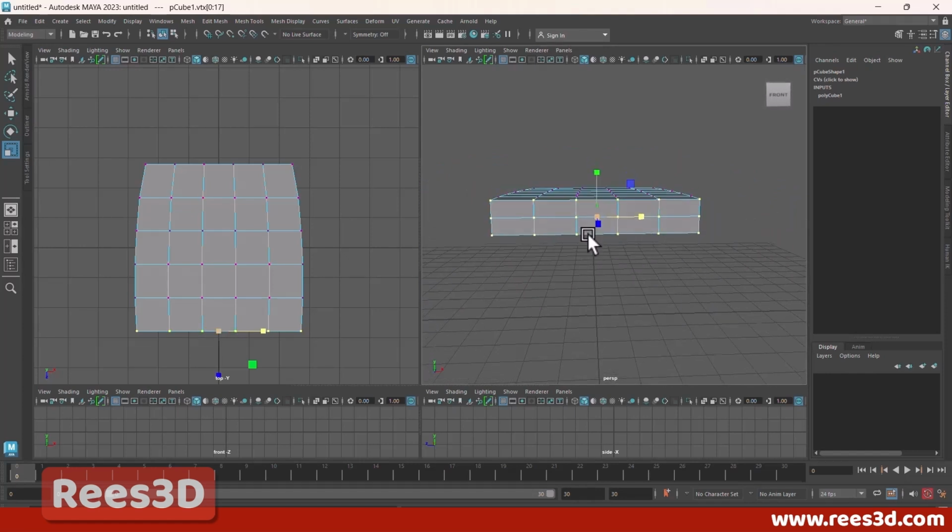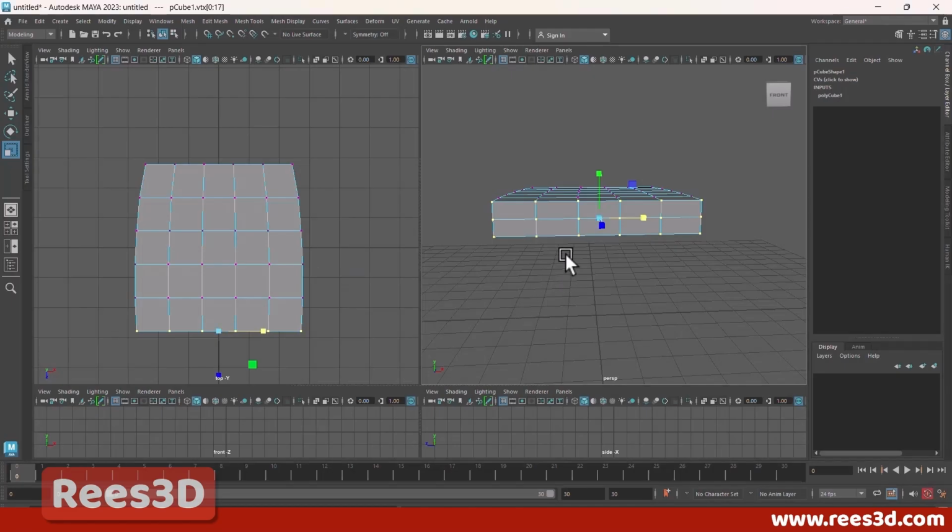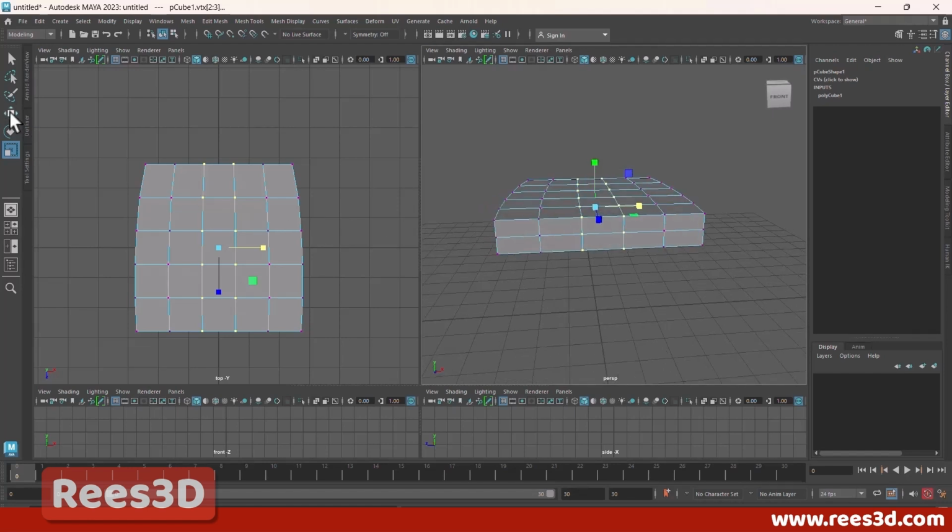This is not absolutely necessary because you can see that it looks almost straight, but there's a slight bend going down right in the middle, right? So we can create that look by selecting all these vertices. Keep in mind, you can use the edge mode also to make these changes. You can also use the face mode, so keep in mind, in case you don't like to use vertices, you can do the same change that I'm doing here by using the edge mode.